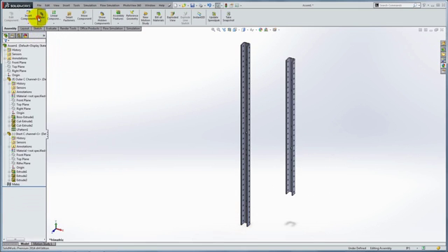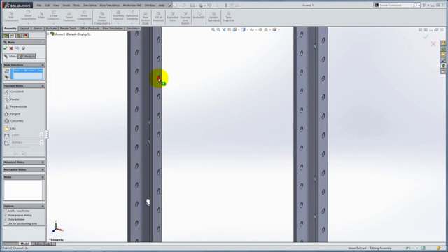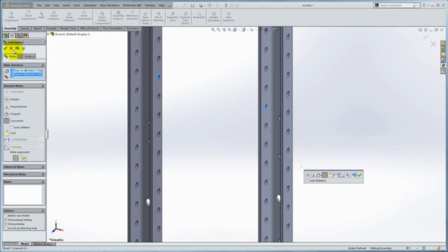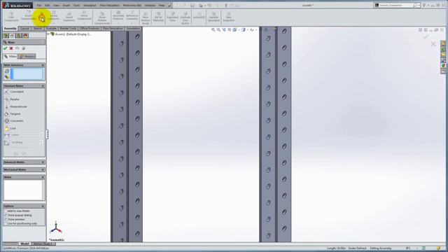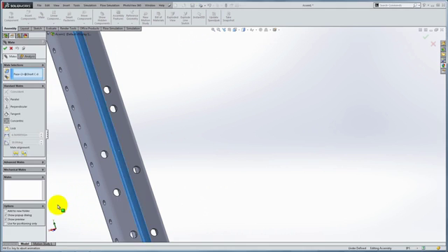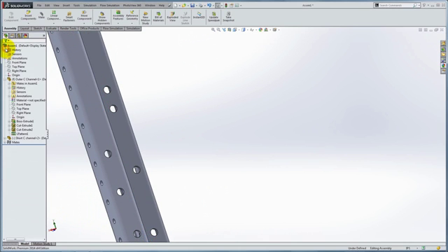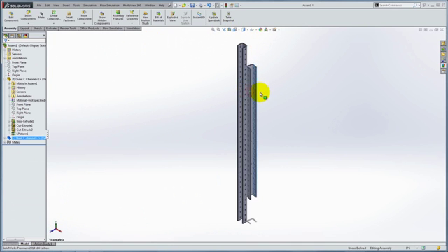The concentric mate is usually used with arcs and circles, and makes them have the same center or axis. While the tangent mate is used between curves or circular surfaces and lines or planar surfaces. To edit or delete a mate, expand the Mates folder in the Feature Manager and right-click.